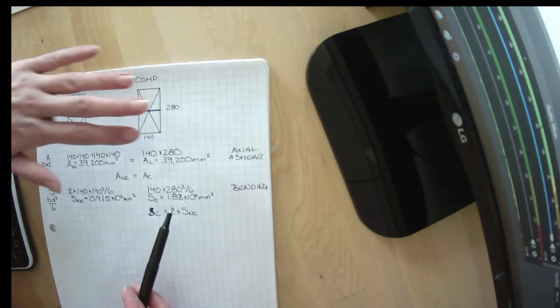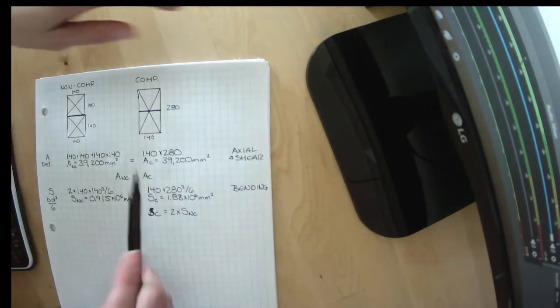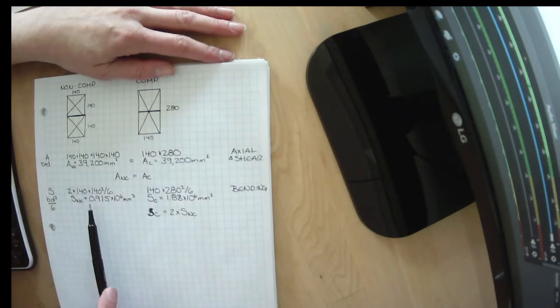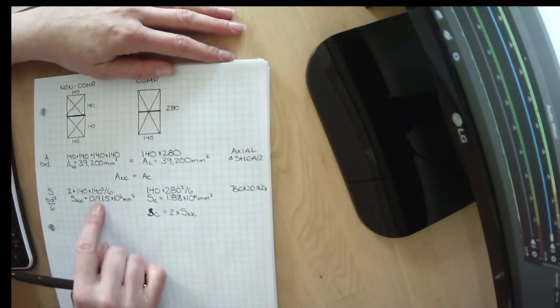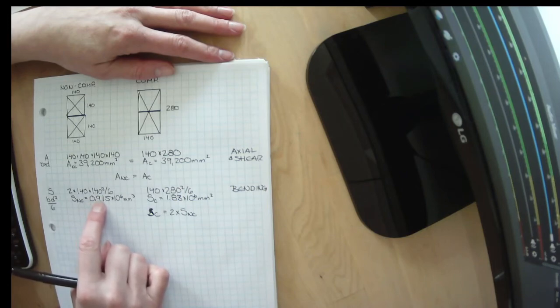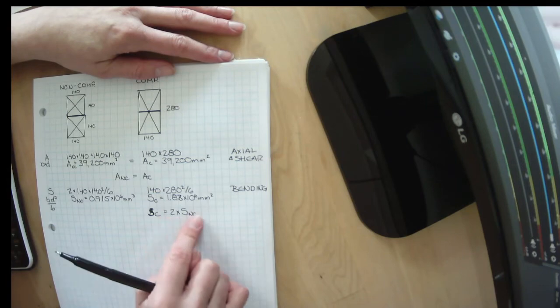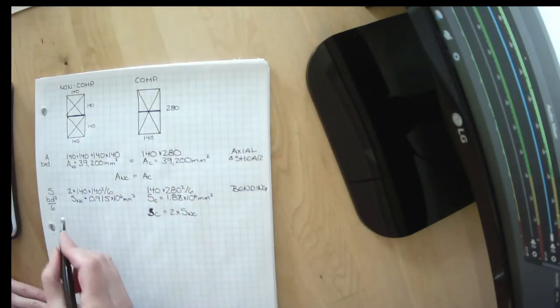So we have the same amount of material in both of these. The difference is that we've bonded it together. Not bonding it, it's worse than one. The section modulus would have been half of this. But by bonding it together, we actually have increased the section modulus.